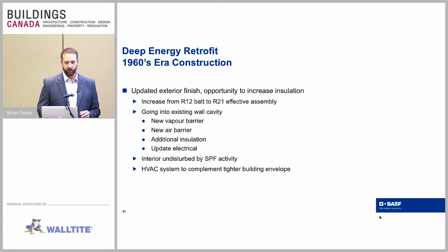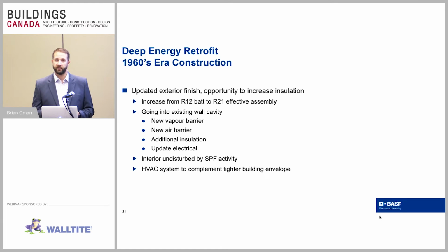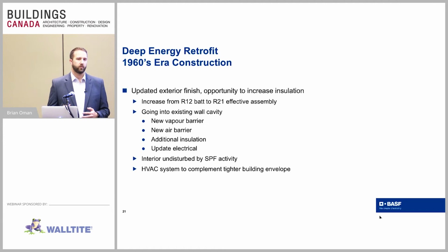So a couple of things about this sort of a retrofit. It is scalable. We'll talk about that a little bit later, but the big thing is we're going to be able to greatly increase the R value of this existing home without really changing much about it. The look of the home afterwards won't look much different, other than it will have a fresher face with new siding on it. One of the big things we're going to be able to do is make sure that the wall assembly is properly protected. We're improving the overall energy efficiency of that structure.